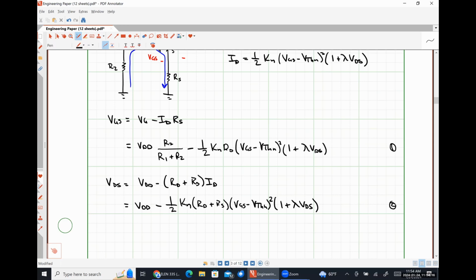So these are all of the different ways that the 4-resistor bias network can bias the transistor, effectively. Without channel length modulation in saturation mode, things are fairly straightforward. Literally any other case, so triode or with channel length modulation included, we wind up having a system of equations that we need to solve, which means it's computer science. If I were you, I would do like I did and set up a MathCAD sheet where you just plug in the resistor values and let the computer do all the work.